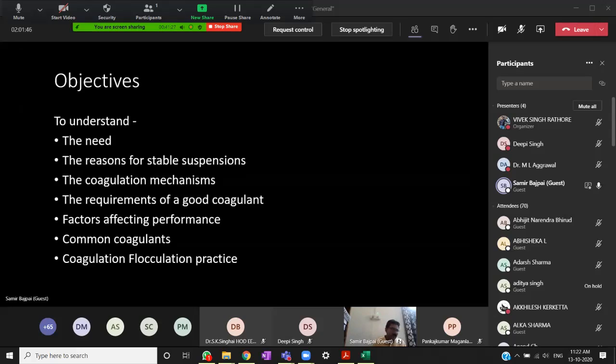So these coagulants are attracted to these particles and they form a sort of bridge. And this bridge is known as flock. The result of this bridge is flock, and this flock then attaches other particles, and then it overall becomes a heavier particle and settles out. And this is known as coagulation, flocculation in our terminology.